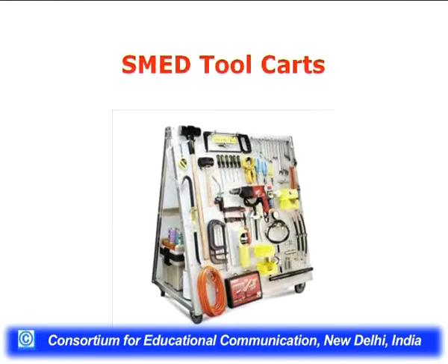And SMED tool carts, these kind of tool carts are used in the factory, and let us spend some time on the design of the tool cart. For each changeover, a separate tool cart can be designed, or a common tool cart can be designed. This is a tool storage area which includes and displays the tools which are required during the changeover. These tools are displayed on a board where we can see the particular tool to be used, and the area where it is going to be kept on the tool cart, and a boundary or outline is also marked on the tool cart.